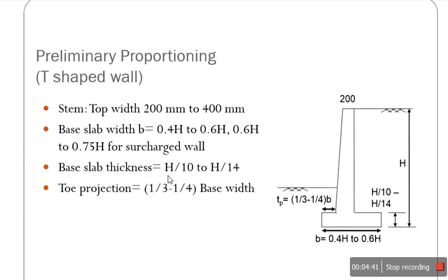If the conditions of your retaining wall are stable, then we calculate those moments. If you are going for a limit state design, then you will calculate the steel as per limit state design. If it is working stress, then I will calculate the steel as per working stress design. So these are all the steps which we normally follow.